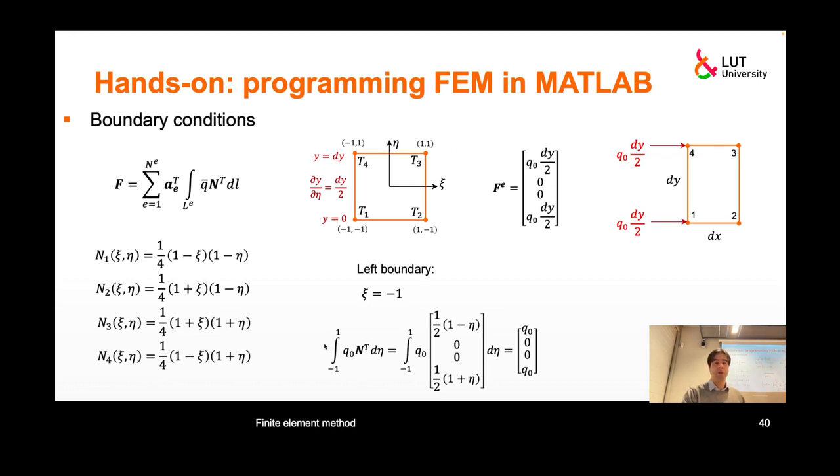So if you want to have the value of this integral in global coordinates, even though the directions are the same, still there is a scale factor, so we need to have this Jacobian matrix, which is this multiplier in this case. Determinant of Jacobian matrix, in this case, Jacobian matrix consists of just one element.